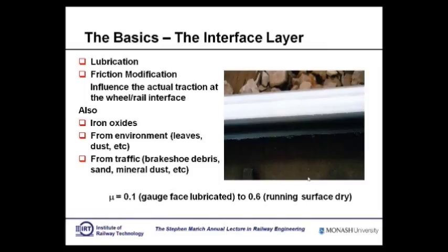That's essentially what they always say. It's a bad month of the year kind of thing. We have caterpillars going from one side of the track to the other, and therefore we're going to get wheel slip occurring. I mean, obviously. You don't run trains when the caterpillars are on the move. And you've got brake shoe debris, sand, you've got dust and so on and so forth.